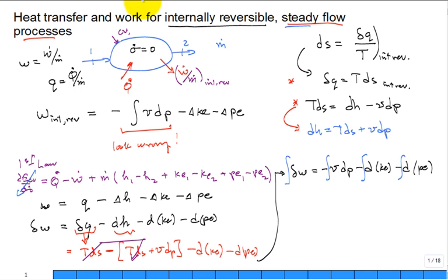And so this would be the small w. This is restricted to be internally reversible. Sometimes it's emphasized with that subscript on that w, is equal to minus the integral VdP, that surprising term that looked wrong, but there it is, minus the change in the kinetic energy minus the change in the potential energy, and that's usually the symbol the mathematicians put, QED, right?